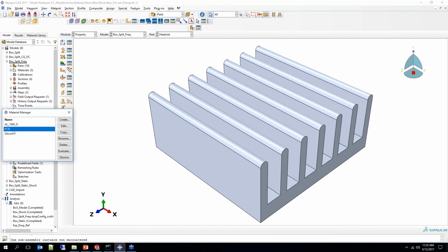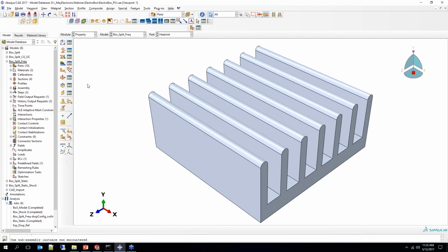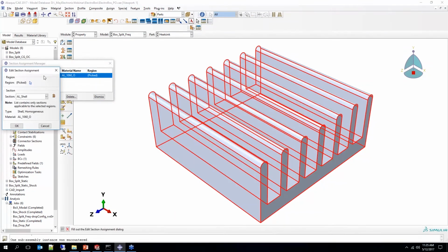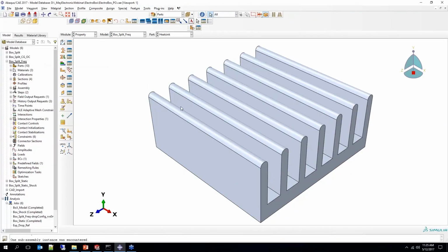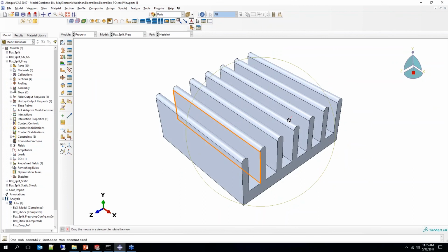So it's a novel, unique element type to Abaqus, but what it allows you to do is quickly set up these parts with aspect ratios that are better for shells. The scale of the model is such that you have a thin plate that's very long, and to mesh adequately through it, you'd either need many elements to get a few elements through the thickness and capture the length appropriately, or use a thing like continuum shells.